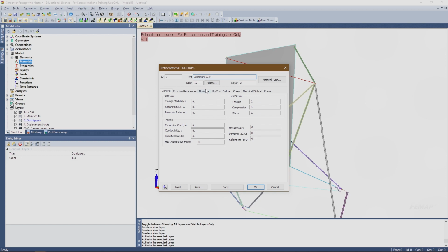So an aluminum plate that is greater than 6 inches will have different strength values than an aluminum plate that is less than 6 inches of the same alloy. If it's in the form of tubing, it'll have different strengths. So generally you want to be very clear, like plate 1 to 3 inches or something like that.